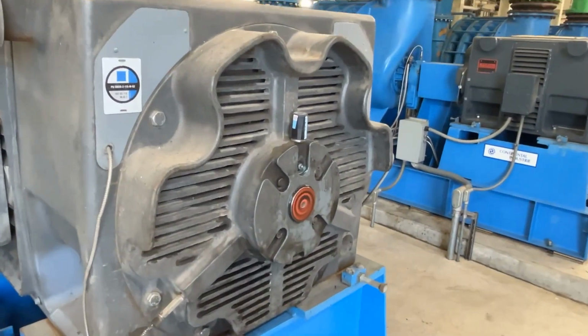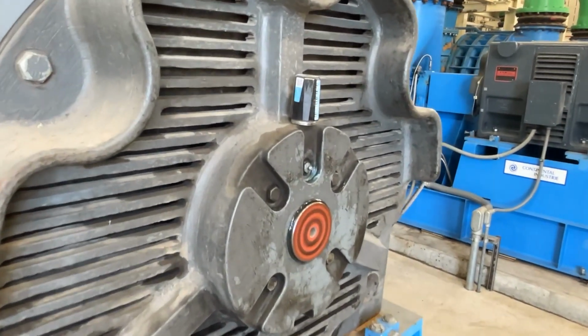Are they monitoring both ends of the bearings, like on motors? We are. We're doing free end, load end on the motors and free end, load end on the blowers as well. So there's a total of 4 per unit. On our gearboxes, on our contact basins, we have them on the motors and upper and lower on the gearboxes as well. And I believe there's one on the center to monitor gear mesh too.